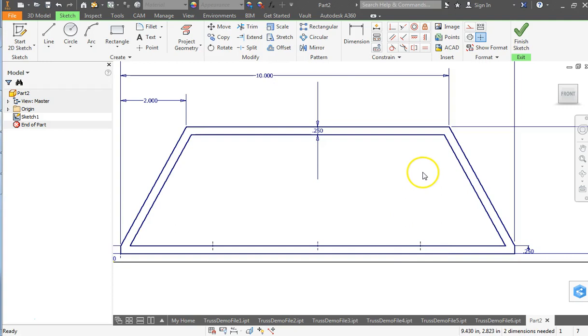Now, instead of using the dimension tool, I can actually use the vertical align tool, and I can say I want that point to stay vertical to this. Now this will move here. This won't move to it because this point is stuck. Remember, we fully dimensioned everything before these points, so I know this point here is the only thing I can move. So that slid over. I'll repeat again with the tool still currently turned on. I'm going to go here to here. That moves. Okay.